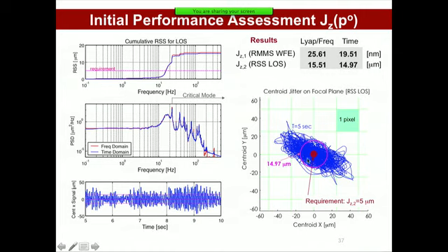So if we look at the pointing, for example, here on the right, this kind of fuzzy fur ball, what does that represent? That's a time domain simulation of the centroid of the image, right? The telescope is now observing a part of the sky, trying to get these early proto-galaxies, and it's flexible. It's a very lightweight telescope. It has these reaction wheels turning, trying to keep it stable. We have electronic sources of noise.